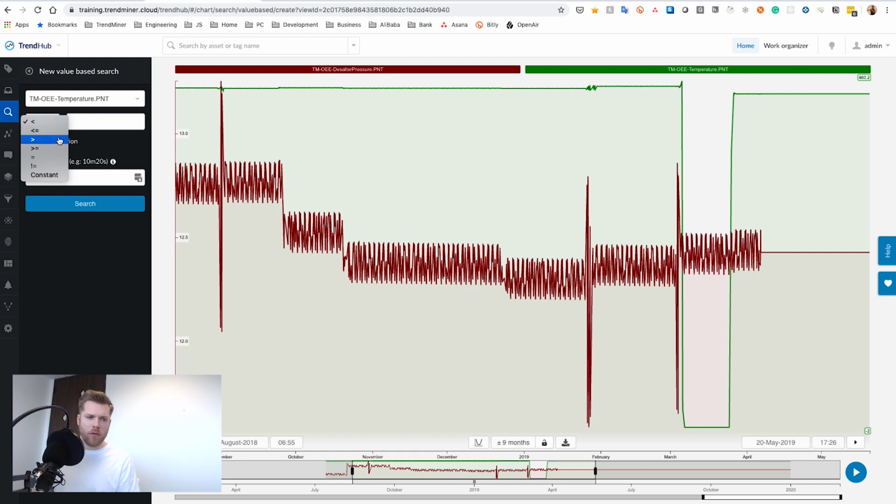And I know from experience, or from my colleagues, that anytime this temperature is below 250 degrees, the furnace is basically turned off and it has to be restarted. So I'm going to add 250 as a condition there. And just to avoid any blips, any too sensitive events from happening, let's say I just have a little outlier in my data, I will select at least 15 minutes.